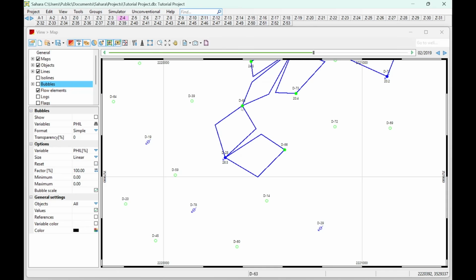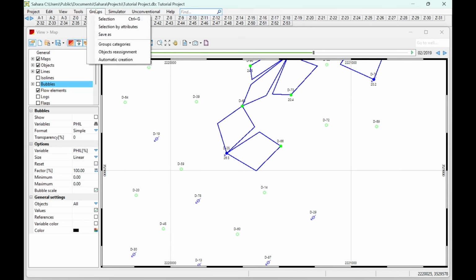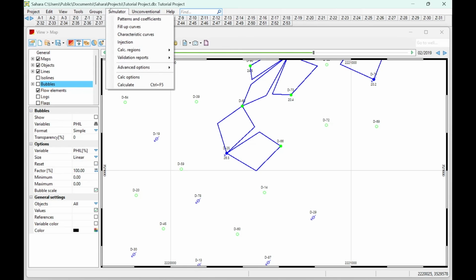So in this case also you're always going to have 100%, same as with weighted by pore volume. With that option as well, you will have 100% of your total water injected in that layer affecting totally the associated producers with the flow elements.